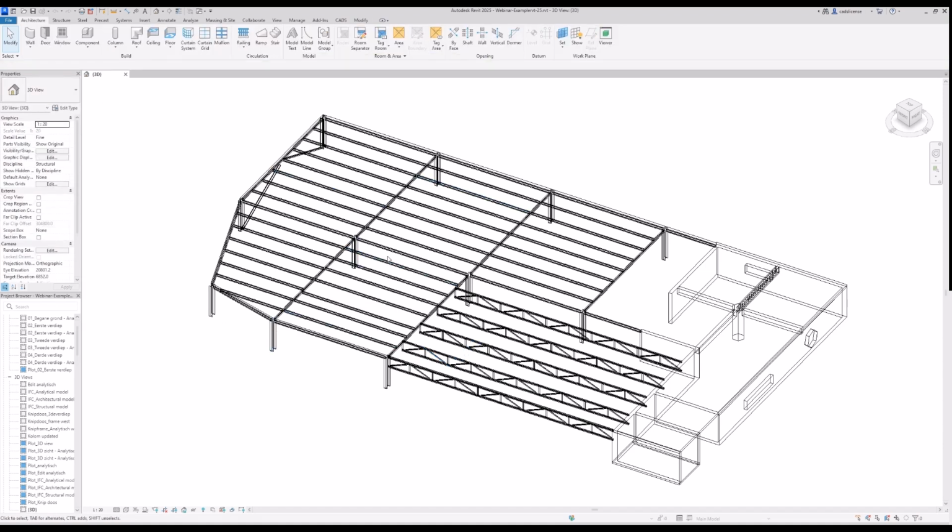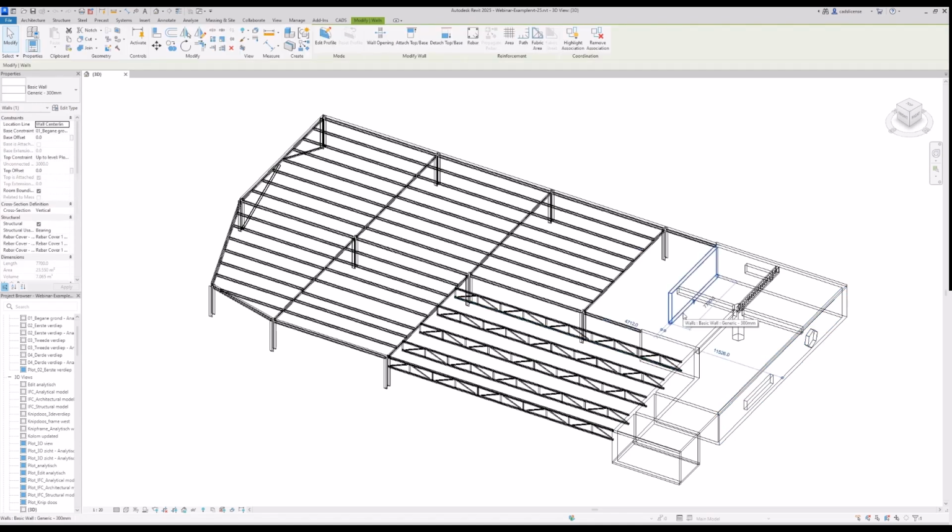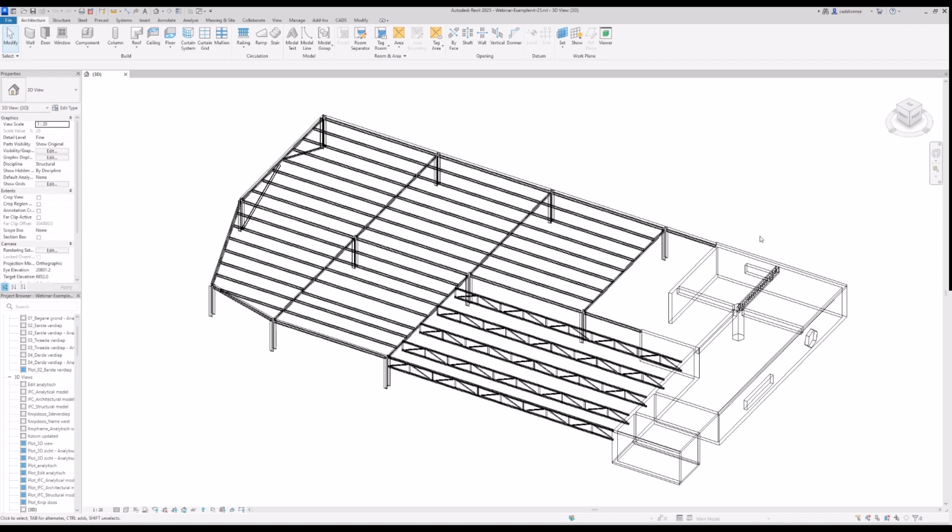On the left of this structure, you find the concrete part. This concrete part has a few walls, all with a thickness of 300 millimeters. In those walls, you will find some openings, both openings which are rectangular and one opening which has a hexagon shape. These shapes will be exported to SCIA Engineer later on as well.